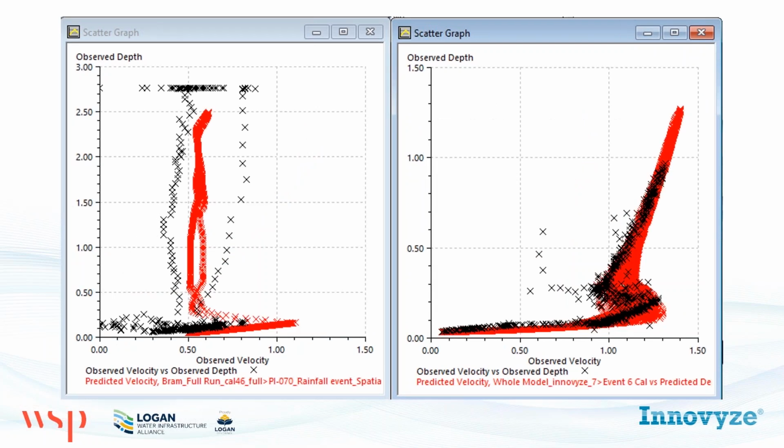Are these particular types of graphs used for movement of sediment and debris? You can also ascertain that kind of performance from these graphs as well. Again, the ADS poster on their website does explain all these in quite a lot of detail. Often you'll see different types of performances from the theory mixed together in the same sewer, but you can certainly see the movement of sediment, debris. You can even pick up large objects or blockages, that sort of thing. They're quite a powerful tool.